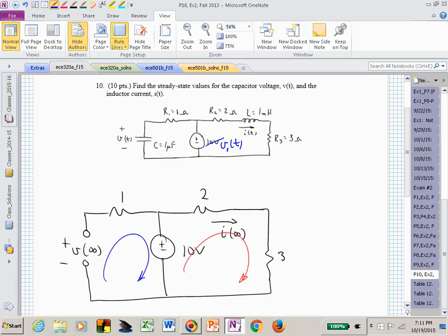We'll look at different V1s. First, we'll give you a decaying exponential. Then we'll give you a sinusoid. Then we'll give you an exponentially damped sinusoid. But you could do all of that once you've solved this once. Now you would just have to Laplace transform different V1s of t's and plug those in and solve the resulting equation.